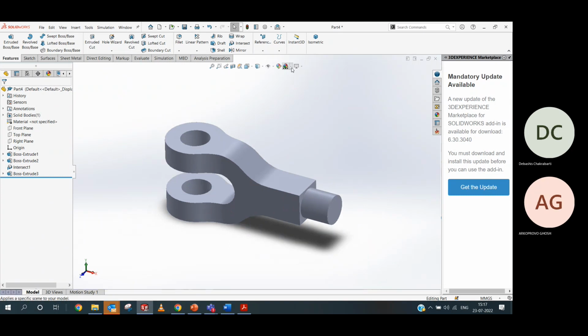So see how to apply some colors on the faces on a solid body. If I have a solid body here, click. You got here the appearance options from your layout toolbar. Just click here, expand, and you just got the faces, like which face you select. If you have to particularly define the color in a particular face, you have to select a face and go over here. You see face or intersected bodies or total body or part. Okay, part, I just want to define in my part.